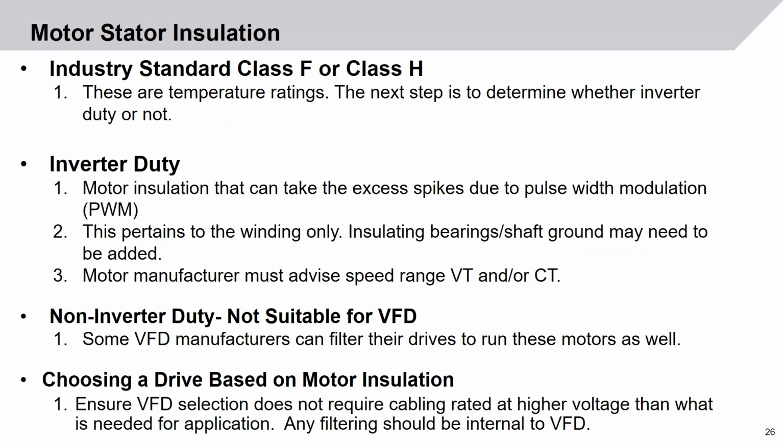To be inverter duty, the motor manufacturer must advise the speed range in VT and or CT. There are some non-inverter duty motors that are not suitable for VFDs. However, modern VFD technologies allow some VFD manufacturers to filter the drives, quote unquote, clean enough to run these motors as well.